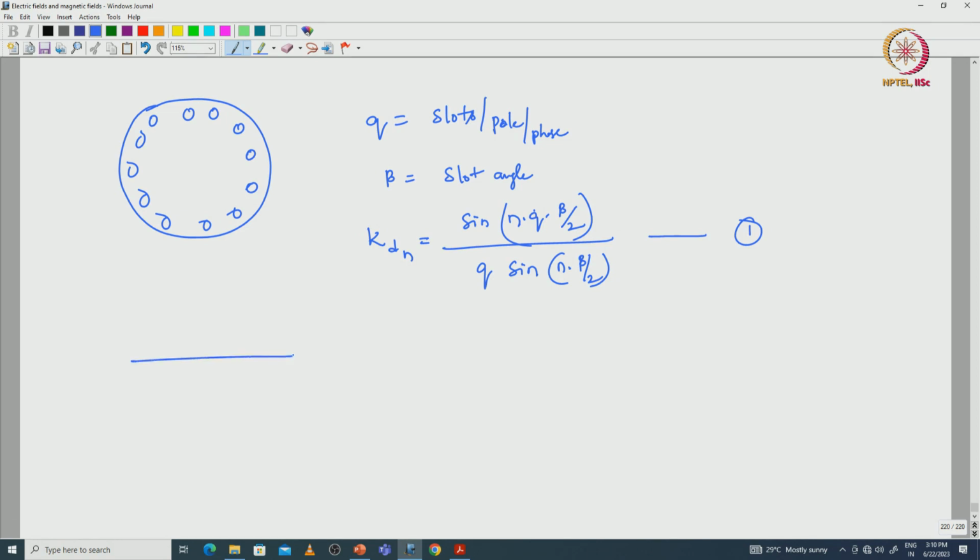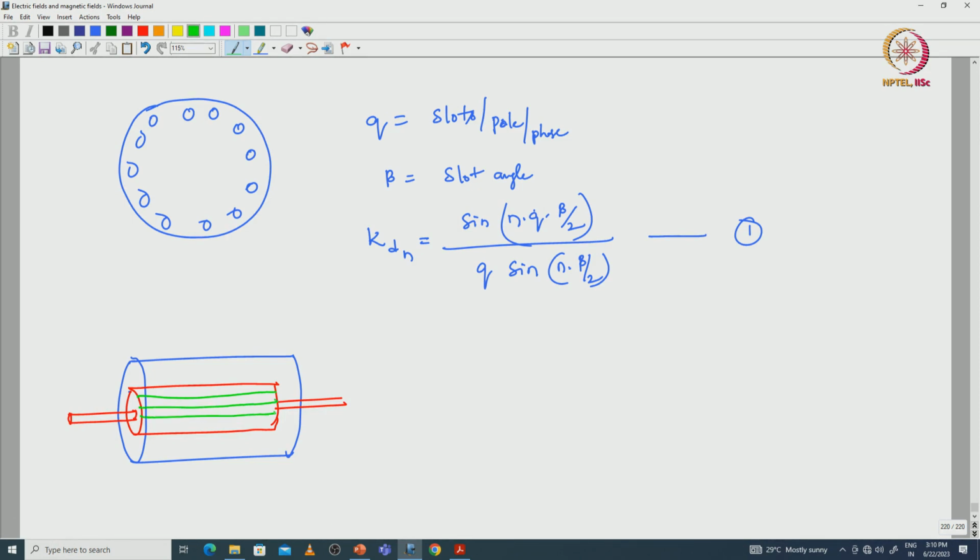Now, let us consider the machine without skewing. This is the rotor, and shaft. Here, without skewing means there is no skewing of bars. We can see the straight bars on the rotor. Here, in order to minimize the crawling, cogging and other effects, we have to select the number of rotor slots appropriately, and the skewed rotor structure we will see now.